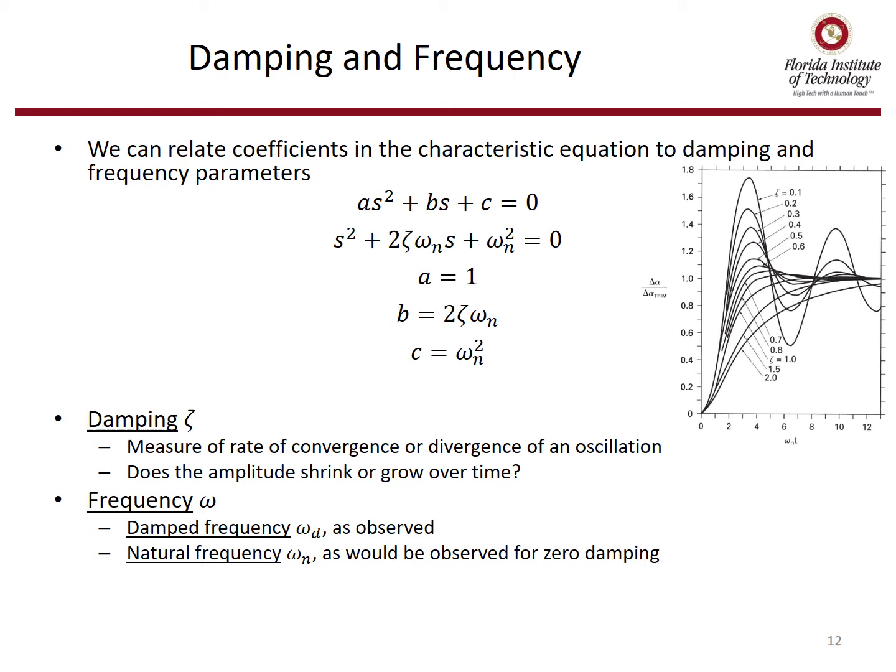The plot on the right shows the different damping ratios of zeta from 0.1 to 0.6, and then eventually zeta equals 1, which is critically damped, and then if zeta is above 1, we say that's overdamped. There will be no oscillations if zeta equals 1 or a number greater than 1.